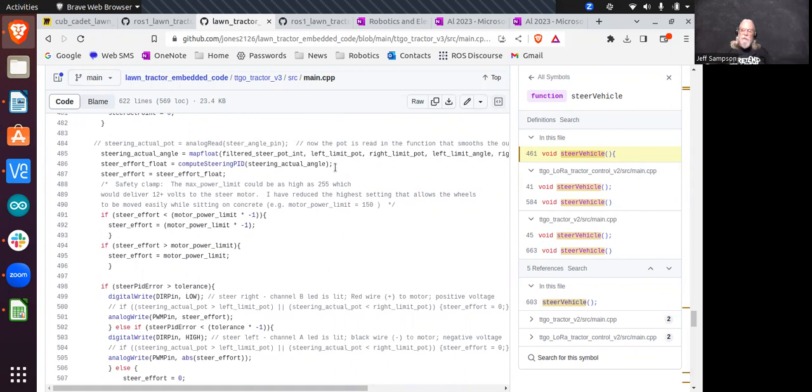And by controlling the value you add each time, you can either make it turn very slowly, or, I forgot what your current value was, last night you were saying 48 degrees. Well, if you put in an increment of 50 degrees, then it's going to do the actual step function. It's going to follow exactly what you tell it. Or you can put in a very small number like 1 or 0.1, and it's going to take longer for it to move out there. So that might give you better control over your steering.